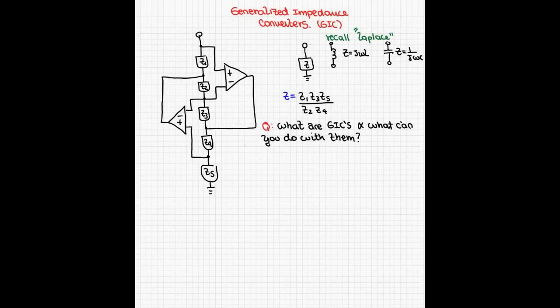Okay, today we'll be talking about generalized impedance converters, or GICs. They also take the name, sometimes when you employ them as simulated inductors, gyrators, or simulated capacitors, or frequency-dependent resistor components. So it will look something like this. You apply a voltage right here, and then you have an impedance that is simulated, and it's grounded.